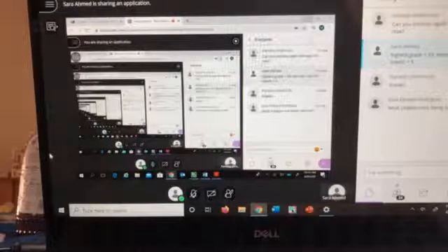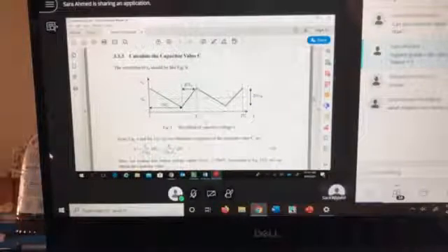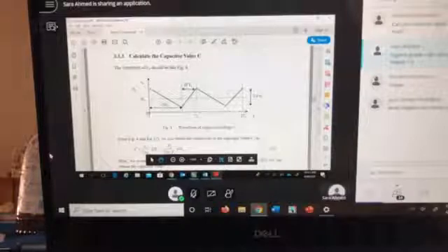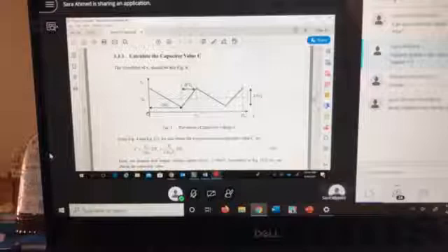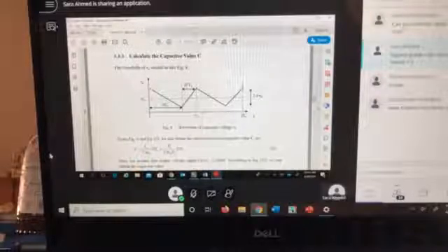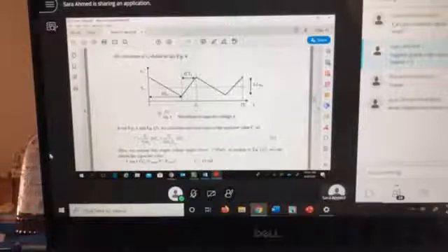Okay, so the capacitor value, what is the capacitor value now? Again, it's the exact same equation, but it is on the voltage. Why? Because C dV by dt is equal to I of C, right? So the current I of C divided by C will give me my change in the capacitor voltage. So this delta V is basically, delta V is what? Delta V is your I of C over C. So I of C, we got it already from the equations for the capacitor charge balance.